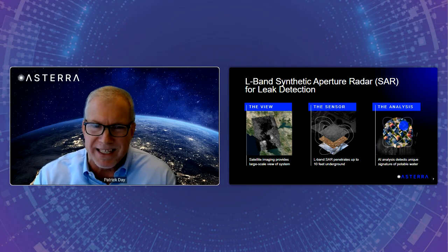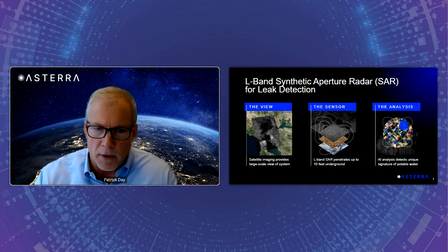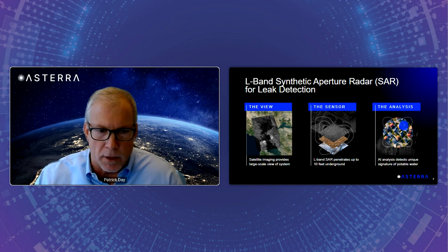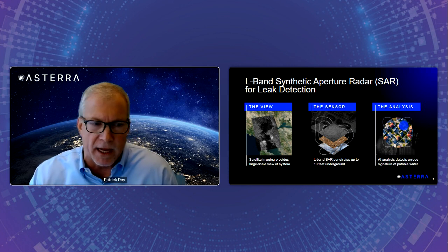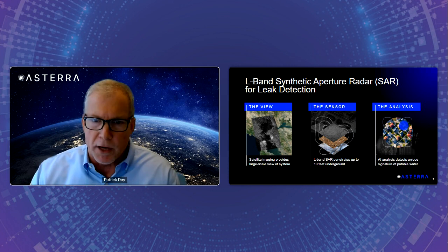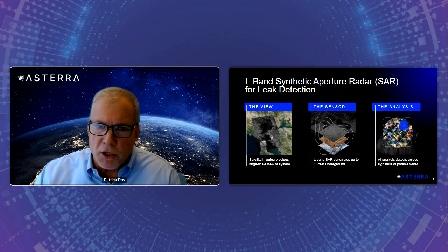We're able to detect what type it is by the algorithms that we're using to scrub the data, and then we're turning that back over as a point of interest for further analysis. And again, that's where the baton is passed to another technology. Most of the time, that's going to be a qualified, competent ground crew that's got state-of-the-art equipment, today's version of the old listening stick and the ground microphone, and they're able to investigate those points of interest and confirm for X marks the spot, dig here.